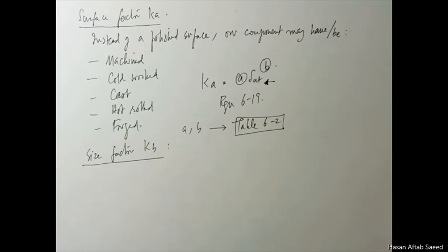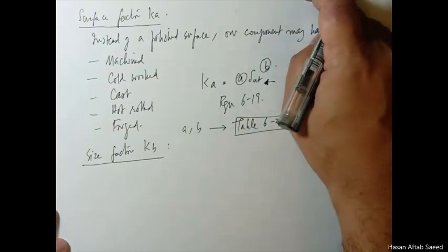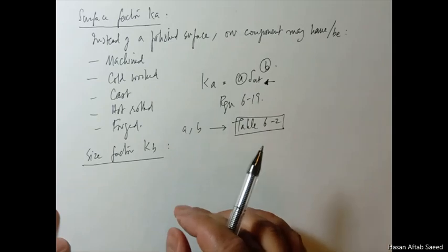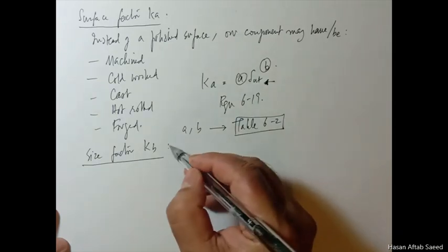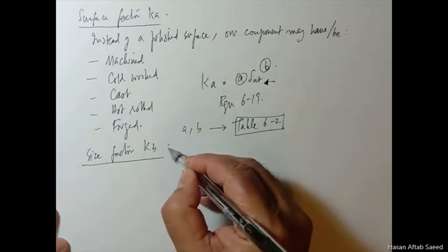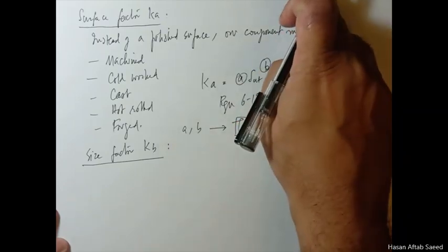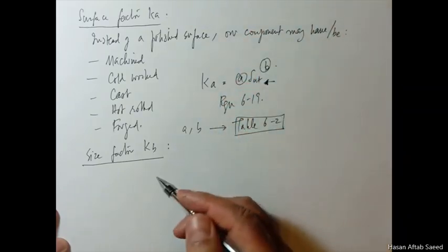So it's not something that is certain. It's still something that we talk about with some sort of probability. The bigger the specimen size, the lower should be the endurance limit. And maybe you will have some components which are bigger and their endurance limit is higher, but that is statistics. Most of the cases of bigger sizes will have lower endurance limits.